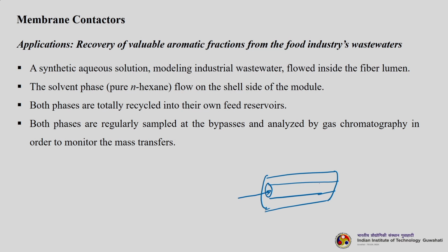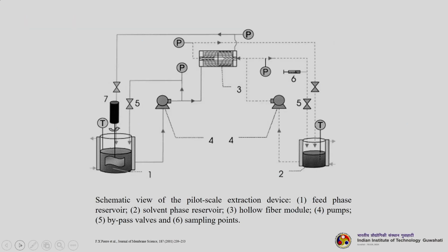So, something is here and something is here. This we can say is the n-hexane, and this is your feed. Both the phases are totally recycled into their own feed reservoirs. Both phases are regularly sampled at the bypasses and analyzed by gas chromatography in order to monitor the mass transfer. So, this is a more complete schematic diagram.